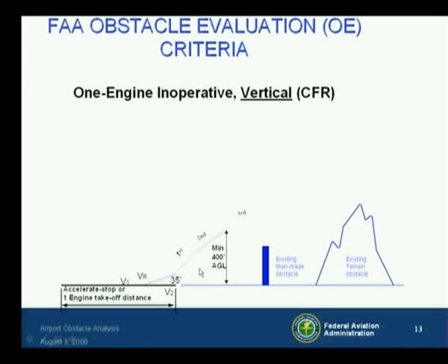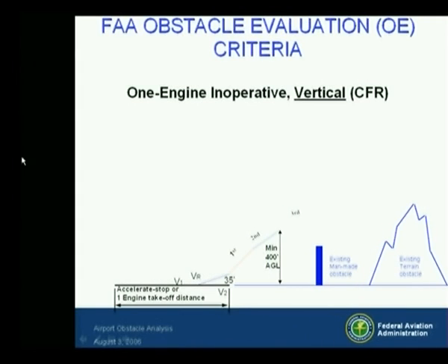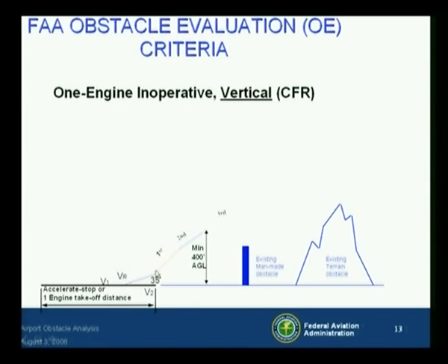The point at 35 feet is also called reference 0, because this is when segment 1 begins. Part 25 prescribes 3 segments in the climb out profile. Segment 1 begins at 35 feet, and the airplane should climb out at a speed as close as practical to, but not less than V2, until the selected acceleration height is reached. So this whole segment, the first and second segment, is flown at V2.